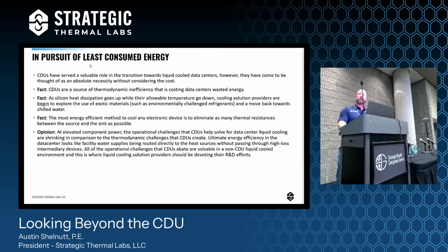Yeah, so pressures are obviously going up. One of the things that CDUs provide is a separation of high pressure facility water supplies. Building water pressures are high because they have long flow paths to push water through, right? And they have a lot of devices on those networks, so their differential pressure winds up being quite high, and the facility water pumps can operate at 100 psi static pressure in some cases.